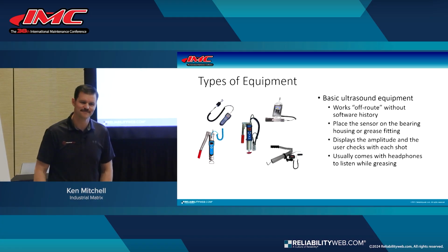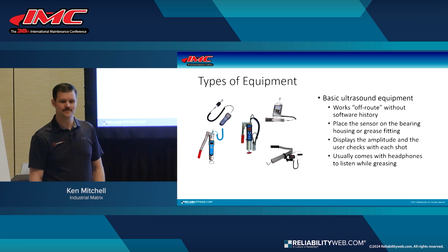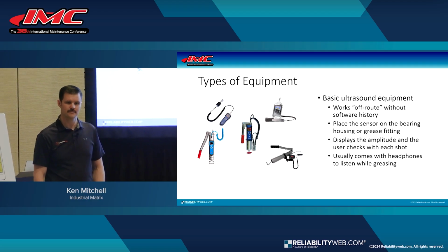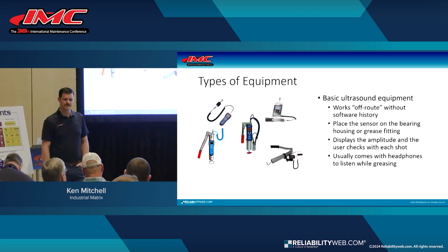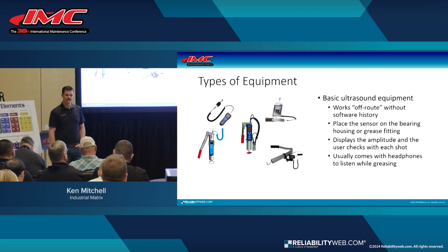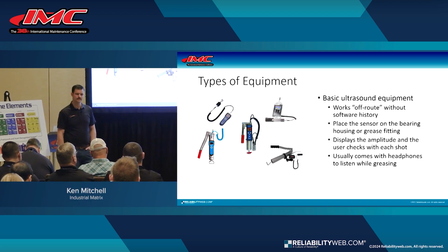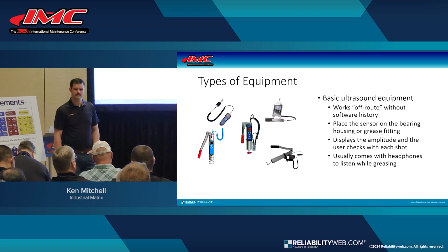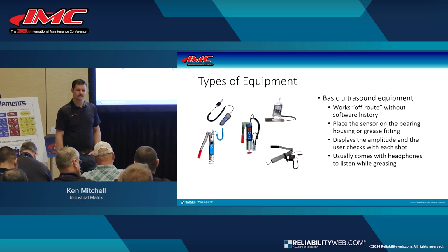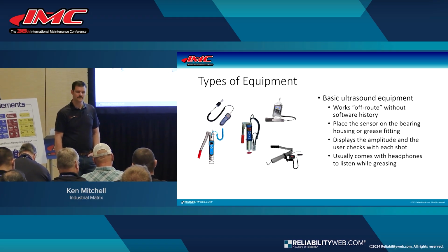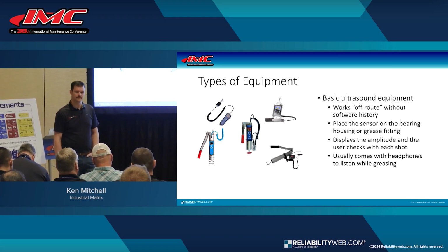To add on to the lubrication housekeeping, we found that having a lube room specific PM, whether it be monthly or whatever, adjusted depending on our intervals, is a good time to fill our oil storages. It gives technicians time to filter new drums that have come in, and it gives you a chance to clean your lube room and make sure everything's ready to go for the next technician that might need it. So we found having a PM for that really does help. Is that like a monthly go-through of the lube room?